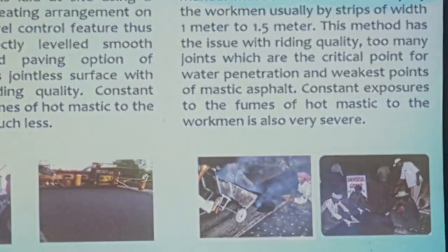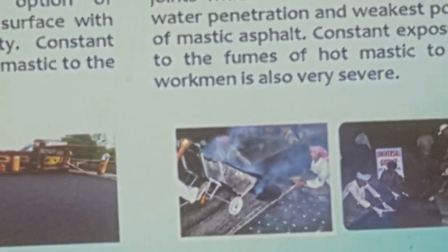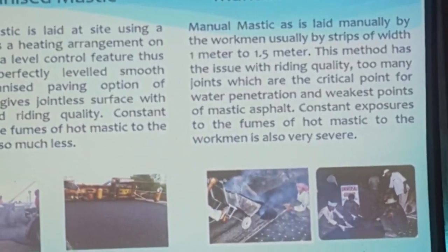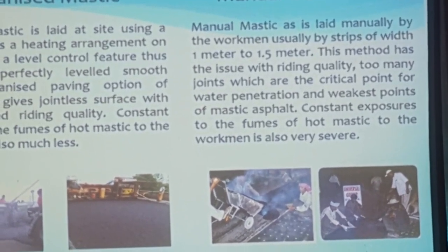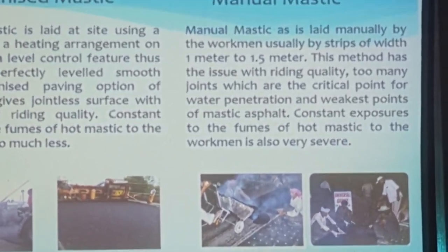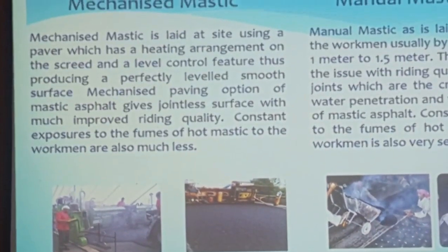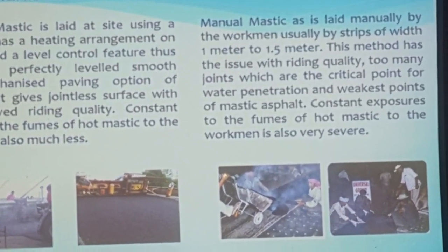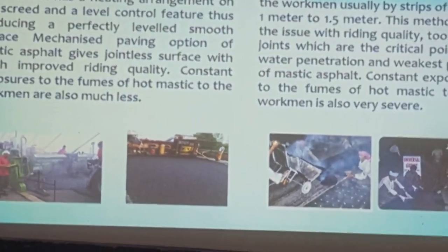And this is the laying of the mastic asphalt. In the mechanized version, it is laid with your paver, and the other one is manually laid. Apart from your riding quality, you can see in the right hand side picture a lot of fume from the hot bitumen. It is inhaled by the workers, and it is carcinogenic. It is cancerous. So health hazard is there. That's why in the advanced countries, Europe, America, it is not that popular. In Europe, it is all mechanized.